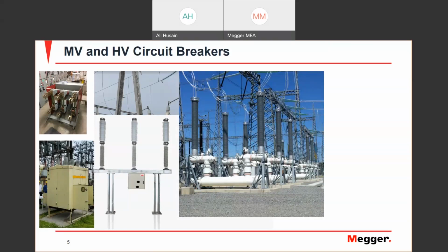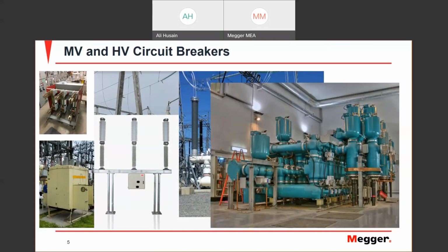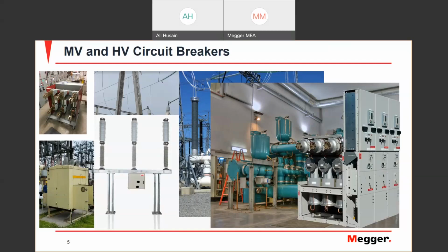And then you have, which is the most common in our region for at least high voltage systems, full GIS systems, where you have all your switchgear and bus bars integrated into a gas, usually SF6 gas. And also nowadays you are finding medium voltage or distribution systems in GIS as well, not just the rack in rack out system.